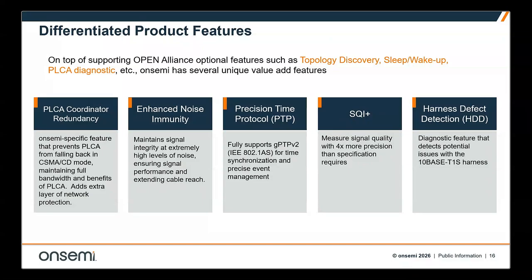Second is the PLCA coordination redundancy. This is a patented onsemi feature. If the PLCA coordinator fails, a backup node automatically takes over, so the network never falls back to CSMA/CD mode. This means you keep the full bandwidth and deterministic latency at all times, adding an extra layer of network protection.